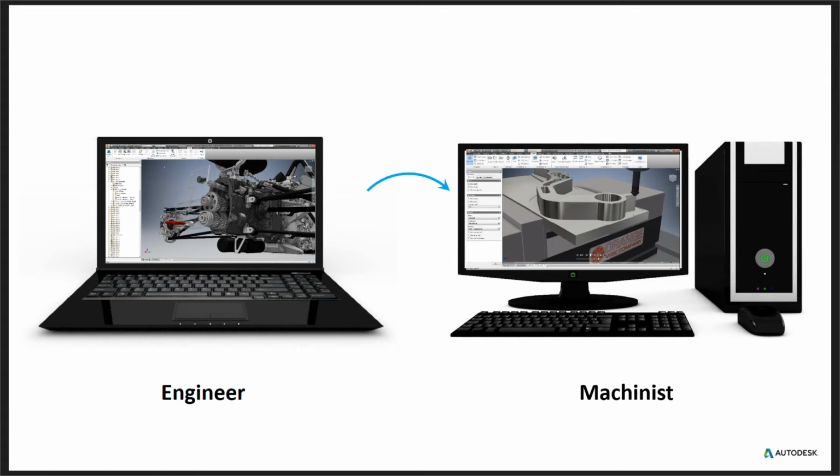And so if the machinist says, hey, I can't actually machine that because our machines are 3-axis, not 5-axis, or I don't have a tool for that, or things along those lines, we hear that pretty often. With tools like Inventor, even tools like SolidWorks and Fusion, you can build pretty much whatever you want. Whether or not that's actually feasibly machinable or manufacturable is another story.